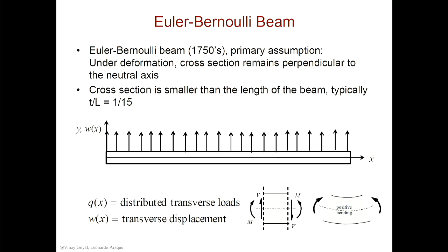So the first one that we'll be discussing today is 1D Euler Bernoulli Beam, which I covered a little bit about the fundamentals maybe the second week of class. I'll revisit this a little bit with you. In the 1750s, Euler and Bernoulli looked at this modeling approach, a simplified approach to the problem by representing a beam, in essence, that represents the behavior of the 3D solid. And it only depends on the x-coordinate, along the length of the beam.